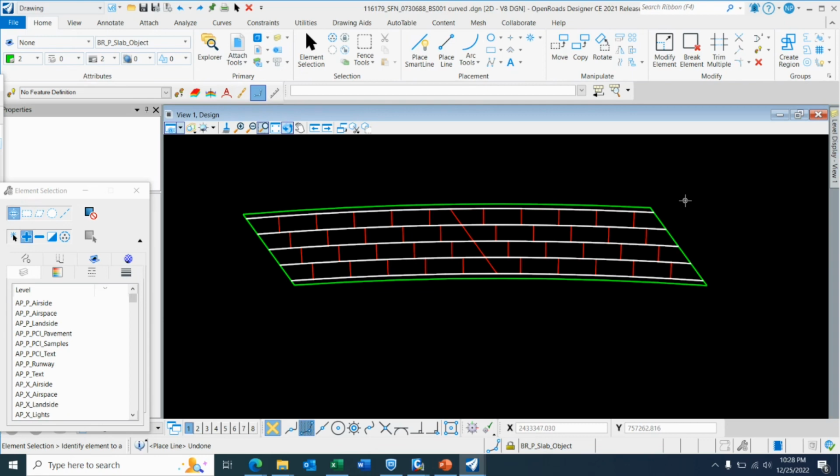To see how Midas Civil Wizard does model cross beams, I did a quick modeling of a simpler curved bridge using the Wizard tool and found out that Wizard actually draws 5 feet cross beams based on 5 feet width at the center line of the bridge.